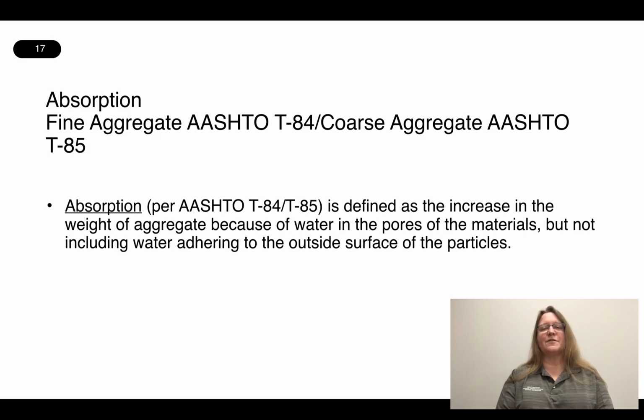So this tells you the definition of absorption. You have a particle, and the particle has a certain amount of pore space, and so the pores can absorb liquid, water, or in the case of asphalt, binder. According to how much pore space the particle has, that will affect how much liquid the particle can take in.